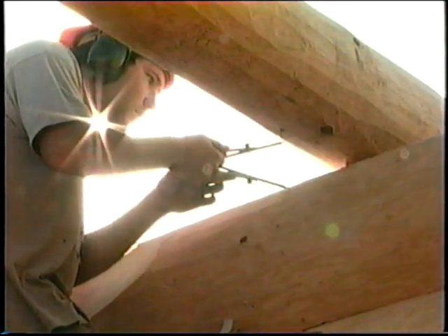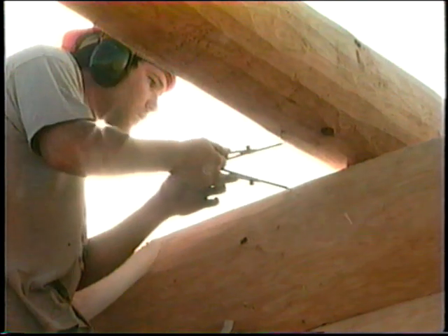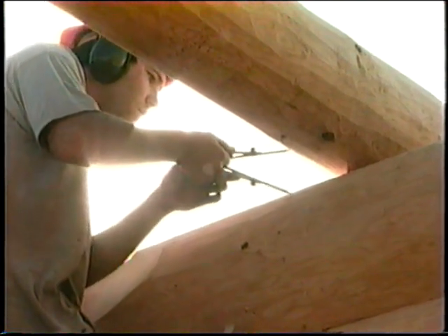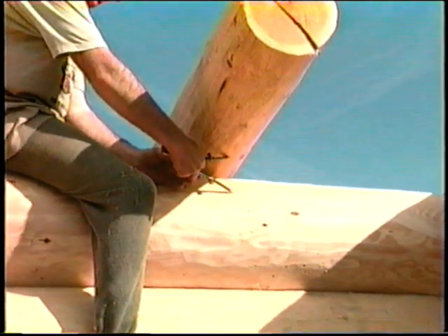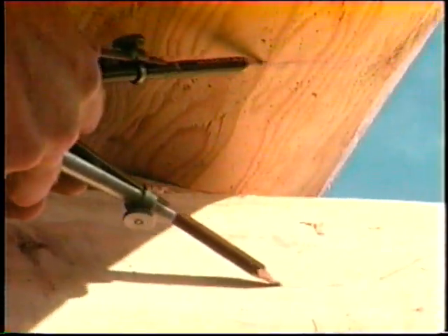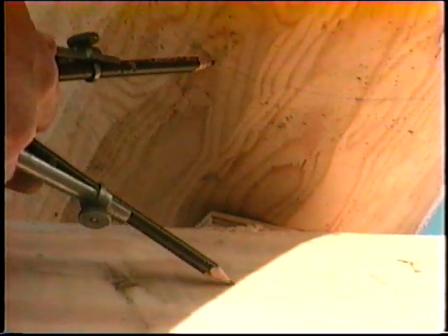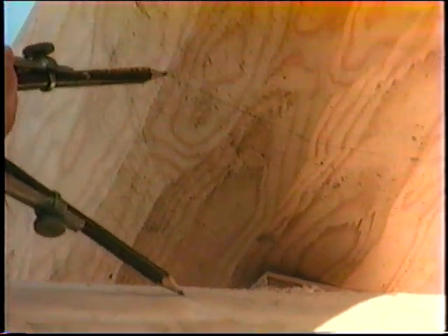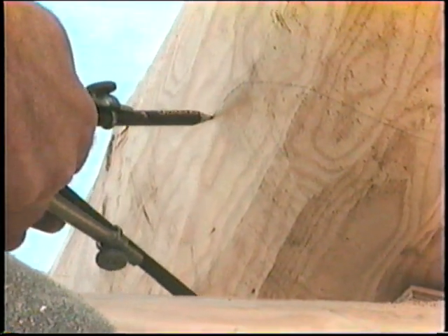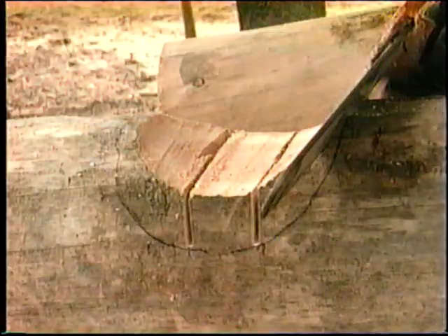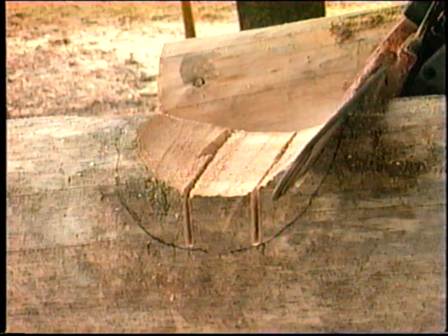When all your joists have been positioned and the proper scribe setting noted on the joist itself, set up your scriber and execute a double scribe. A double scribe means to place 2 pencils in your dividers and draw the upper and lower lines at the same time. The details for this are to be found on tape number 5, Other Notches, Part 1.